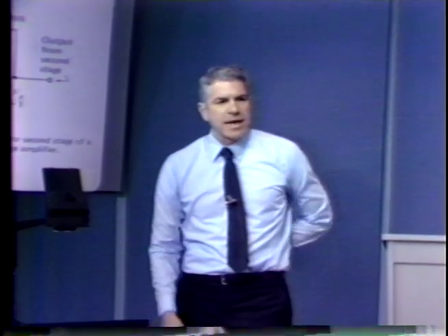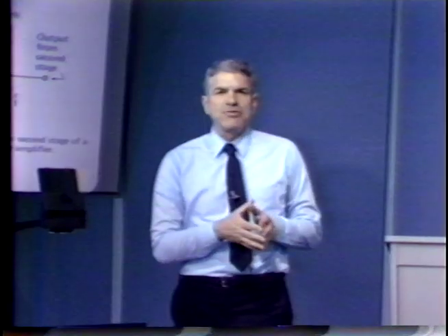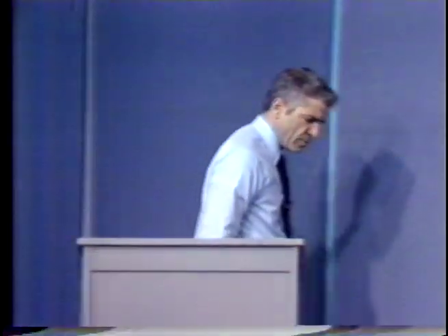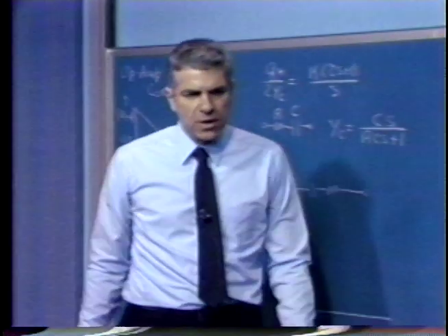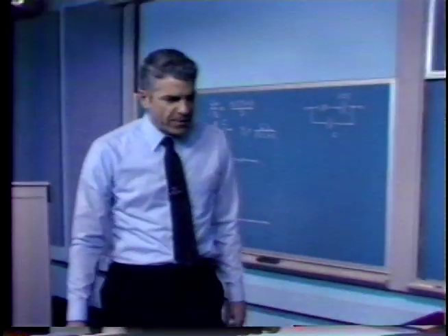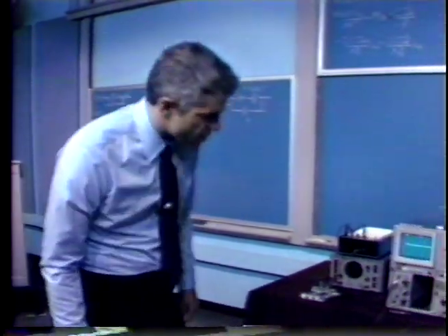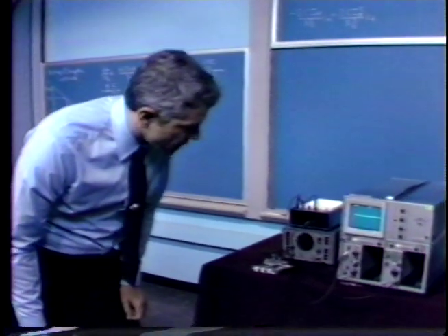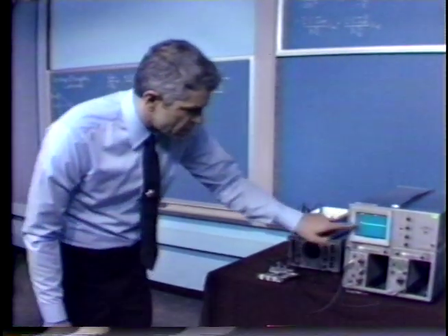I think that what's happening is that if we could physically reach into the amplifier and look at the actual output of the second stage, it'd be oscillating quite violently, an awful lot of overshoot and so forth. We see some remnant of that because we're looking at this through a low-pass filter. Remember we have a 1/10 of a microfarad capacitive load. The ring frequency at present is several megahertz. We're at 2 microseconds per division.